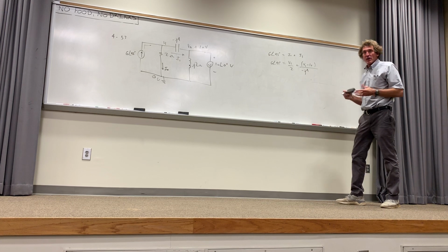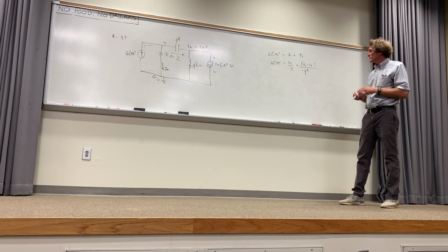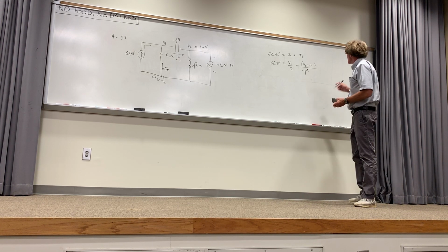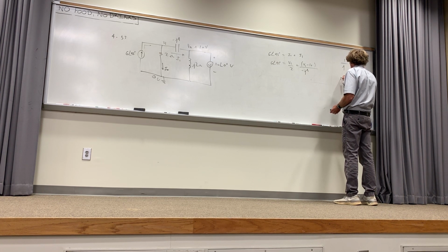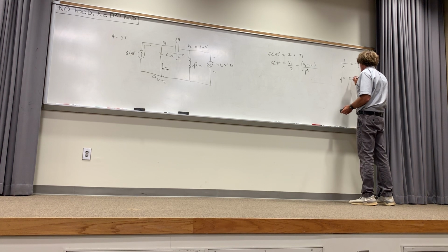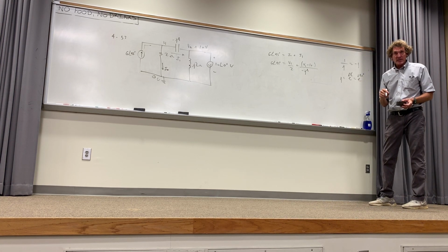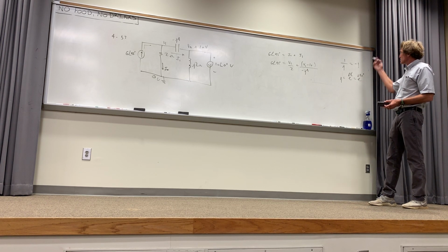Now we're solving for V1, only V1, correct? At this point, it's up to you how to do it. What I would do, to be honest with you, is just multiply. This minus J4, I don't like it. 1 over minus J, just for the record. 1 over J is equal to minus J. J is really equal to e to the J pi over 2 radians, or e to the J 90 degrees, just so you know that. That's what J means. It's 1 at an angle of 90 degrees. Follow me? These are all representations.